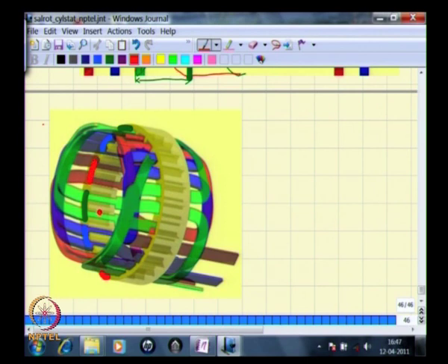So, that would come right at somewhere here. As far as the green phase is concerned, that axis would come somewhere here. Assume that you have a line connecting the center of the stator to these two dots and going out. So, those two will then represent the axis. The angle between the axis is 120 degrees. Remember that this is 120 degrees electrical.